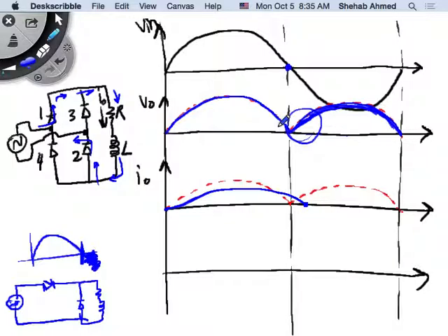Exactly, it will never go down, it will go up again. I'm placing a positive voltage across the RL circuit, right? So if VL is a positive number, VL is equal to L dI by dt, right? So if VL is positive, then dI by dt has to go positive again. It was going negative for a while, but because I've applied this positive voltage across the RL circuit, at some point this current waveform will flip its slope and rise again, and fall beyond where the resistive load would have fallen. But then I'm applying the positive voltage again across it, so it will never fall to zero.